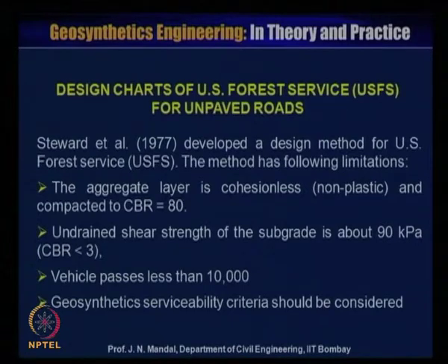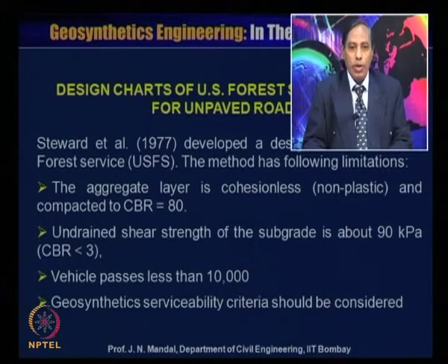The aggregate layer is cohesionless, non-plastic and compacted to CBR equal to 80. Undrained shear strength of the subgrade is about 90 kilopascal or CBR less than 3. Vehicle passes less than 10,000. Geosynthetic serviceability criteria should be considered.